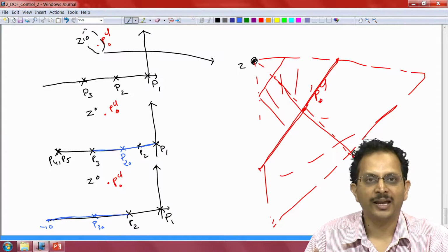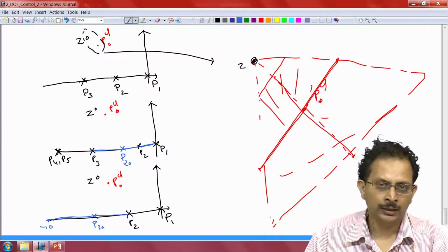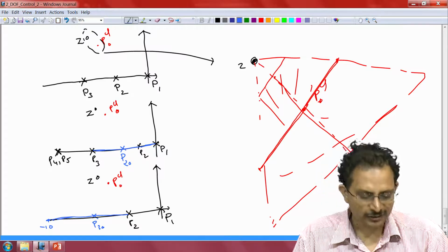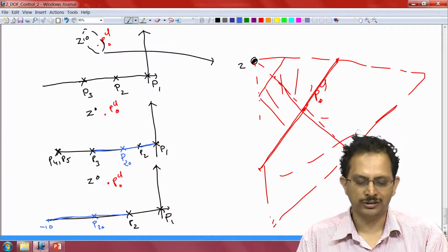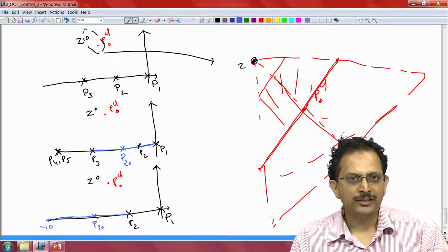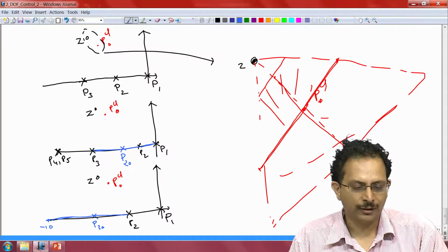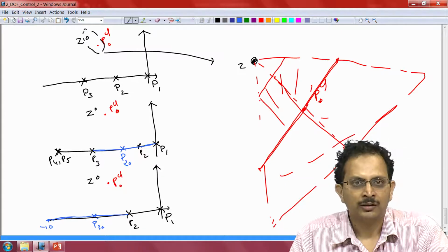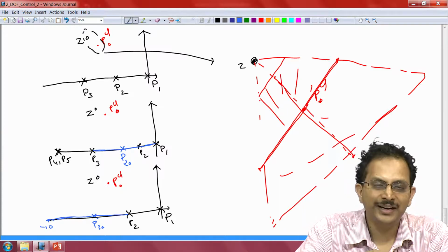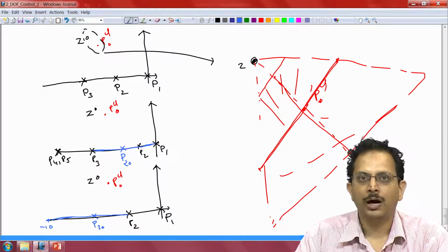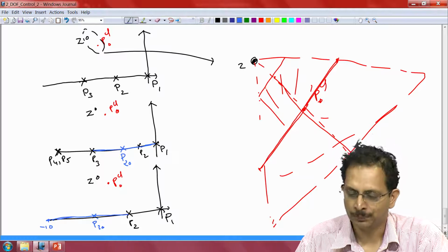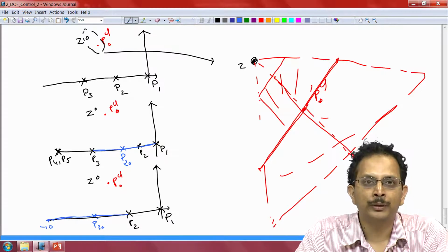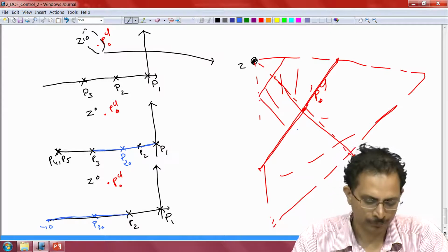Now, the problem of determining the area within which the closed loop pole varies when the second pole of the plant also changes its position is not very different from the cases that we have considered before this. So, for the moment let us assume that the plant gain and the first pole are both at their nominal positions, in which case the closed loop pole would be located at the point PCL naught.